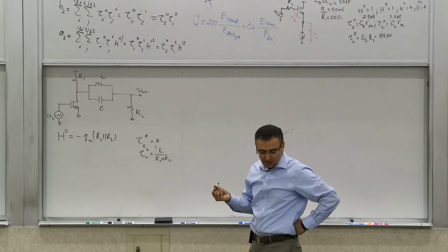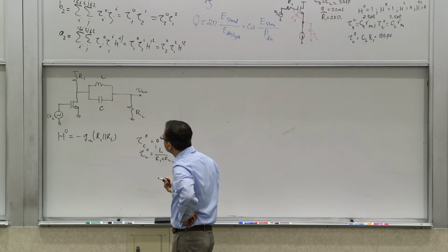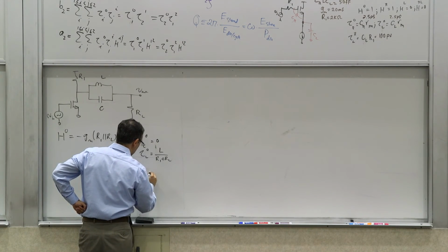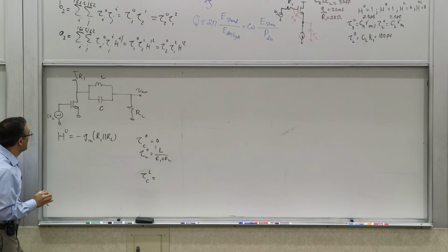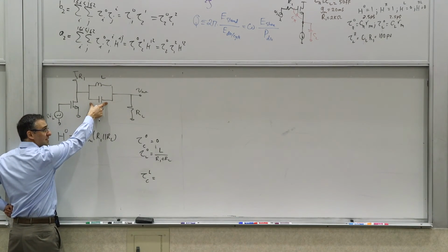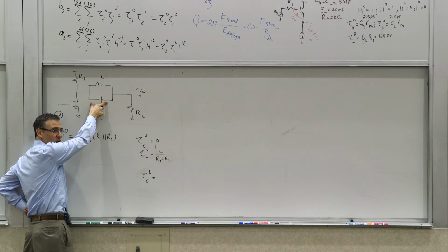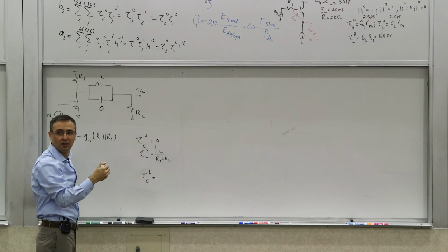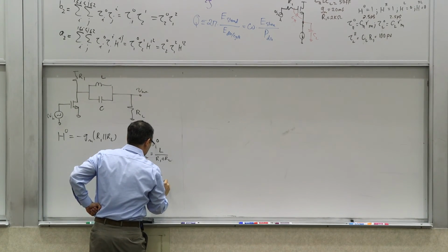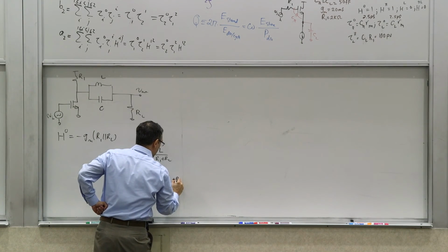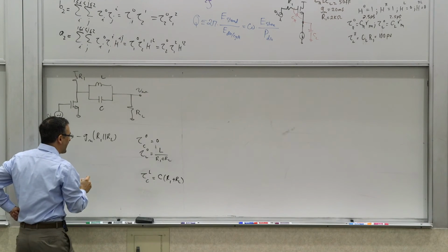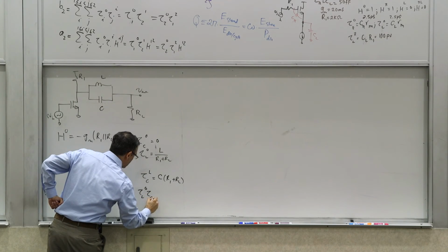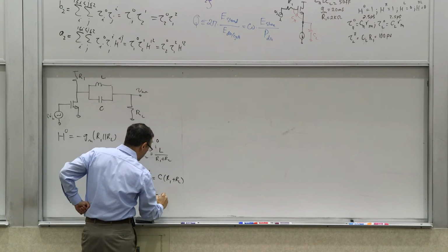So you need to calculate one more, one of those combined time constants, the second order ones, right? So we can calculate tau CL. What is tau CL? The resistance seen across here when L is infinite valued. When L is infinite valued, it becomes open circuit, right? So now what you see is just two resistors. So it becomes C times R1 plus RL. And if you use this in combination with that guy, you get tau L0 tau CL, and these two cancel, you get LC.